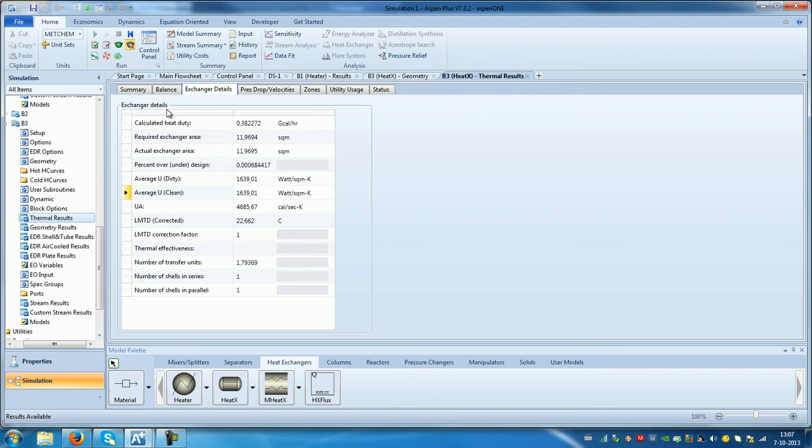But you have to try, if you don't reach your temperature values, or it cools too much, it does the heat exchange too well, you have to decrease your exchange area. And if it doesn't cool or heat up the way you want it, it doesn't have enough heat duty, then you should increase square meters and do the calculations to get your number of tubes and the length and the heat exchanger area.